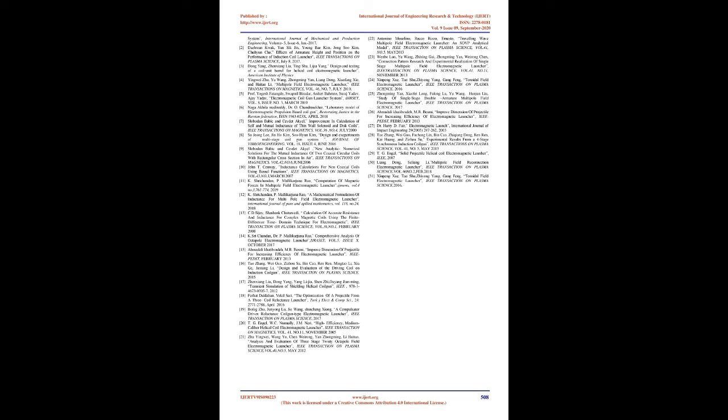If the system is excited by sinusoidal current flowing in a saddle coil moving in the axial direction, each driving coil produces a magnetic field directed along the radius of the cylinder. Thus, radial magnetic flux density with loop eddy current produces a large axial thrust force, and then the radial compressive force decreases. Radial magnetic field can be generated by an increase in the number of poles, but complexity also increases. The connection pattern of the driving coils should generate magnetic field in both inward and outward directions simultaneously to get magnetic line reconnection.